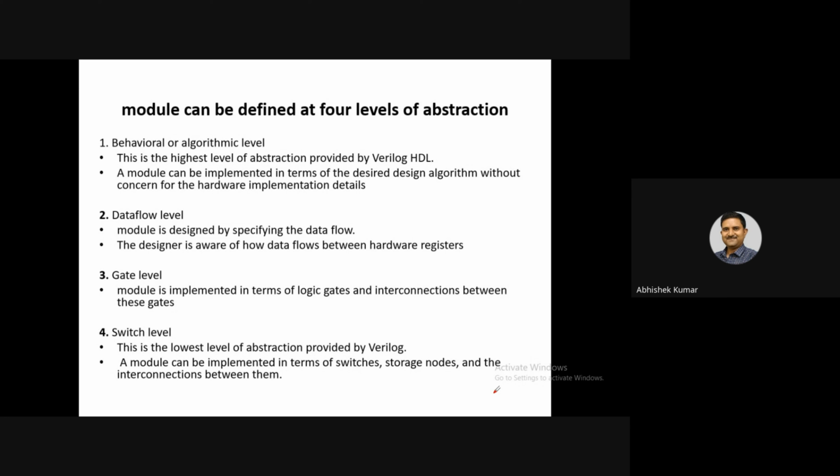Verilog is a language. We develop or model a module in the Verilog language, then simulate it and verify the circuit, confirming that yes, my program is correct. It will do the semantic and syntax check. After that comes synthesis. Synthesis is a process to assure we will get the gate level netlist. It means we are assured that we will get the hardware of the circuit.